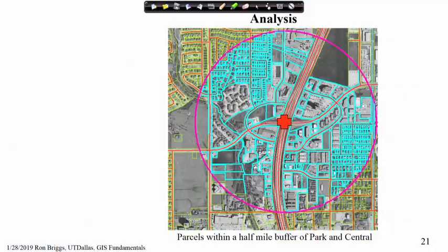And for getting the answers to different queries, these individual vector or raster layers always contain some associated attributes, and these attributes are stored in an attribute table. This GIS software can simultaneously handle both plotting as well as different types of database management. So, it is basically a specialized type of database management which can show different locations giving their proper locational context. That is why it is called geographic information system.